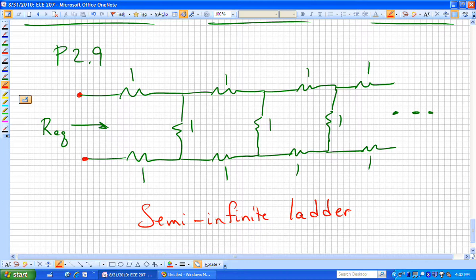Less than 3, based on what we just said about combining things in parallel, because you're now hanging another set of objects in parallel onto that particular point. So you're somehow lowering that 1 ohm resistor with more pieces. But you still maintain those first 2, the horizontal 2. So maybe you're expecting something between 2 and 3.